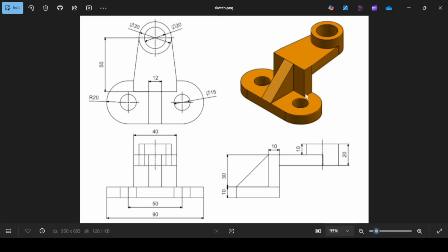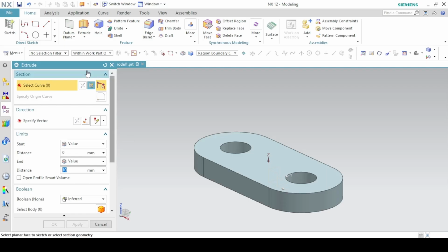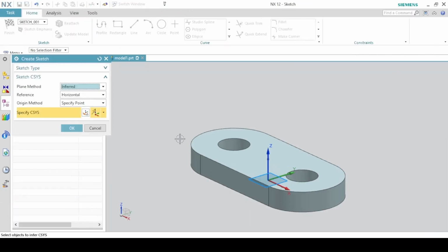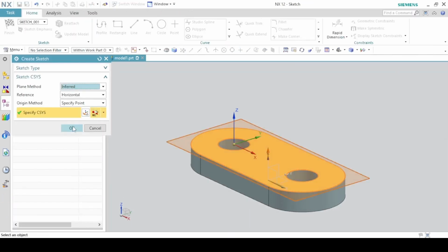Next, you have to draw this vertical block on top of the base block. And then we add the rim. So we draw a rectangle on this face and then extrude upwards by a distance of 30. So we draw a rectangle of dimension, looking at the front view, 40, and then looking at the side view by 10 millimeters, and then you extrude upwards by a distance of 30. So again, with the extrude feature, click on the sketch section. Now come and click on this face and click OK.